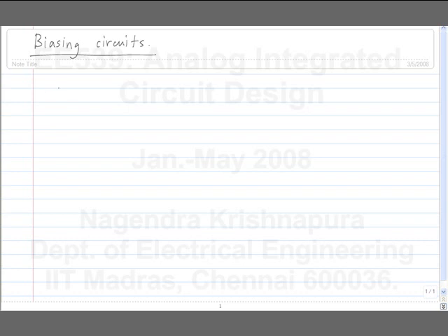So again we will consider this fictitious device which has two control terminals and two output terminals. This is the gate, the first source, the second source and the drain. ID is a function of VGS1, exactly like in a MOSFET, except that we have separated the controlling side and the control side.